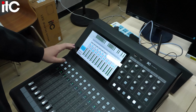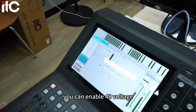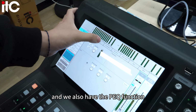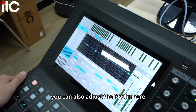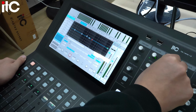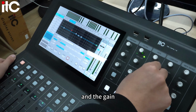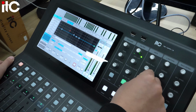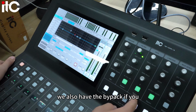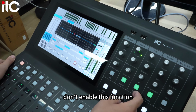At first, we can adjust input 1. You can enable 48 volt, and we also have the PEQ function. You can also adjust the PEQ in here. You can adjust the frequency and the gain, and also the Q. We also have the bypass. If you enable the bypass, it means that you don't enable this function.